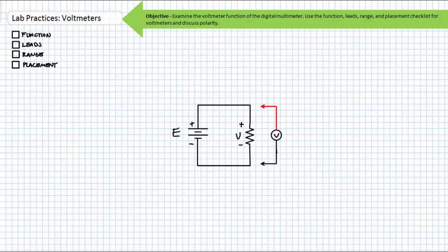Either way, this differential in units of volts is a 2-point measurement and must necessarily be across something. The 2 terminals of a voltmeter simply touch the points of interest, and the voltmeter displays a value in volts. This could be for the voltage drop across a passive element, or the voltage rise induced by an active source.